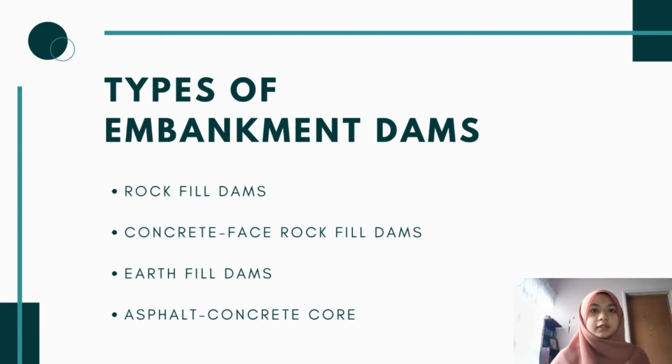Next, concrete face rock-fill dams, or CFRD, is a rock-fill dam with concrete slabs on its upstream face. This design offers the concrete slab as an impervious wall to prevent leakage and also a structure without concern for uplift pressure. In addition, the CFRD design is flexible for topography, fast to construct, and less costly than earth-fill dams.